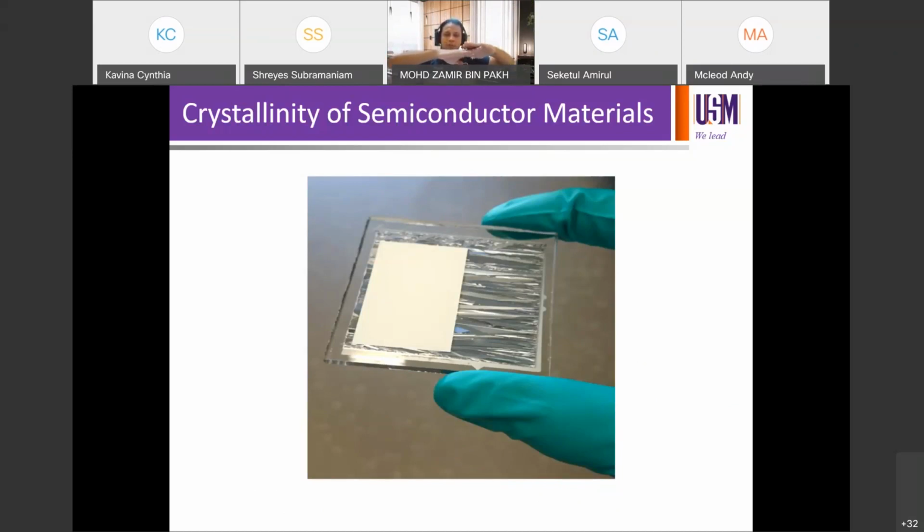So you melt the silicon. So upon solidification of the silicon, it will crystallize. So it'll form polycrystalline. The crystalline orientation will follow the seed layer there, and then it will follow accordingly, and it will form multicrystalline. So that's one approach that we have in order to convert amorphous to polycrystalline. In this case, you can use laser. You can use some other different methods, and each method has its own advantage and disadvantage. So for this case, I use a laser scan, infrared laser, wavelength of 808 nanometer, continuous wave.